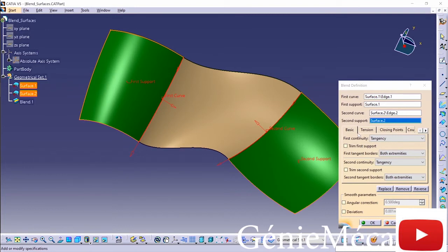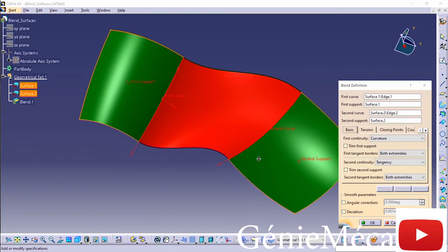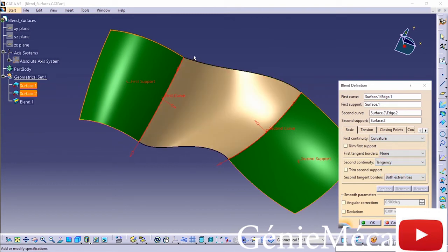I'm going to go back into Freestyle. And in the Freestyle, we have the Freestyle blend surface. And with this, I pick near the edge that I want. Once again, edge, you can see an indication of which edge is going to be selected. And it creates curvature continuity.